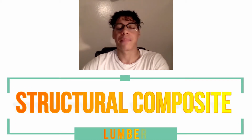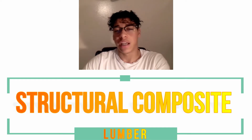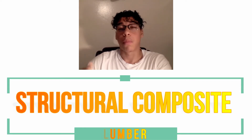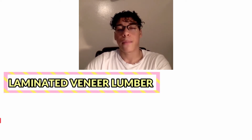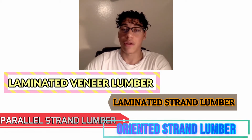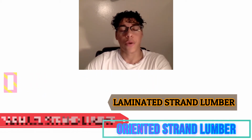which is an engineered wood product created by layering dried and graded wood veneers, strands or flakes with moisture resistant adhesive into blocks of materials known as chunks of wood. And structural composite lumber includes four types, which are laminated veneer lumber, parallel strand lumber, laminated strand lumber, and oriented strand lumber, which I will get into throughout this video.